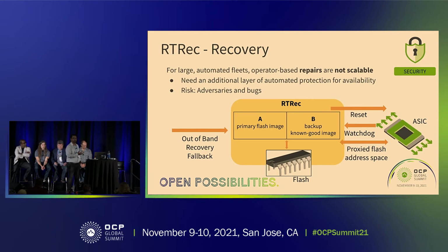One example, simply an example here, is to implement two sectors or even two discrete flash devices. Let's call them A and B. A, which is the primary flash, the machine always boots up and executes out of the primary flash. And firmware updates are always written to flash B. And you can only reboot and update the device if the firmware update has been authenticated.